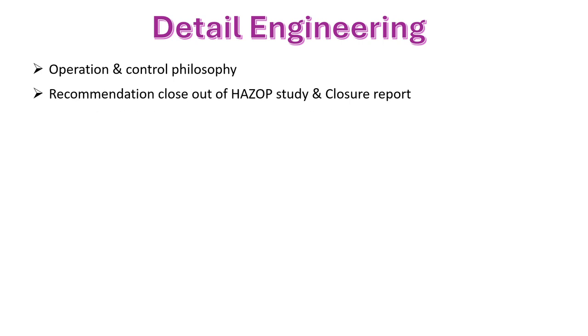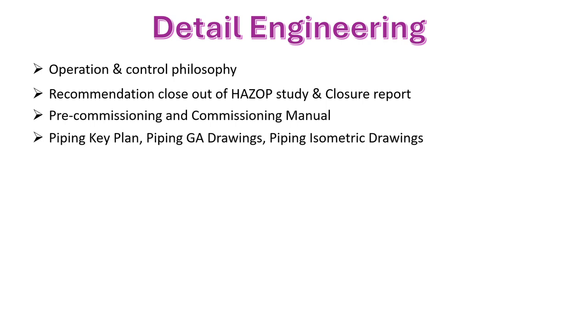Closure of recommendations of HAZOP study. HAZOP study has separate recommendations, so those recommendations need to be closed during the detail engineering. Then pre-commissioning and commissioning manual preparation, which is required for the final completion stage of projects prior to startup. How the trials and commissioning take place, that manual needs to be prepared.